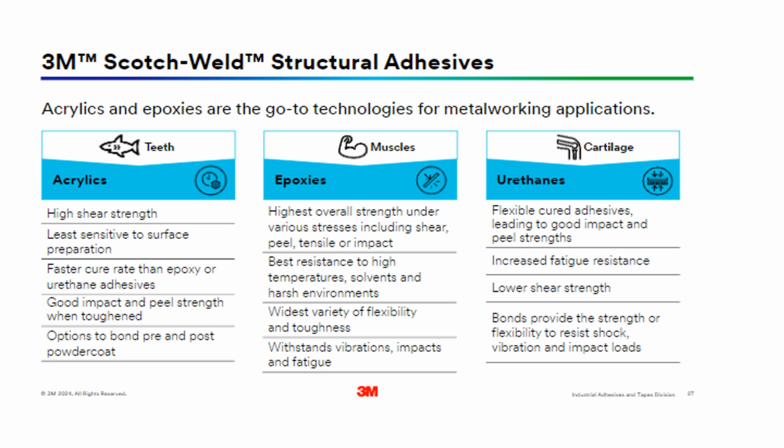They are the most flexible out of the three technologies. So they can be a good solution to bond dissimilar materials because dissimilar materials expand and contract when exposed to hot and cold temp cycling at different rates. However, there are some flexible epoxies and acrylics that we would typically push our customers to just because we prefer those types of technologies. We tend to not sell a lot of urethane technologies.